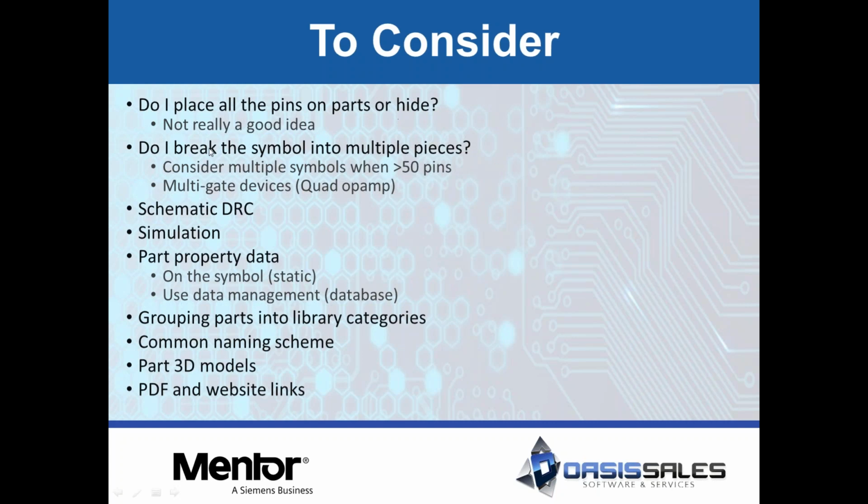So it's a lot easier to say, do the second line: you take a part and even break it up into pieces and put all the power grounds on one part, and then you can make your schematics look nice by having a power ground page, instead of having all the power ground stuff on the part spread out throughout that symbol. Think about putting all of those types of items on its own little symbol and have it on its own page. So it's not a good idea to hide pins.